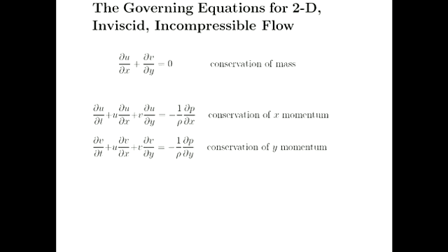That's why we derive it with you in introductory fluids, so that we're not just trying to torture you, we're trying to make you remember all the assumptions you had to make to come up with that set of equations. So there's a lot of them, and I probably can't remember them all, but the big ones are, it's only valid for steady flow when there's no additional energy input into that flow, so no heating or work extraction from that flow. And the really big one that I would have hoped you would remember is that you can only apply it along a streamline. You do remember that? You should remember that, okay?